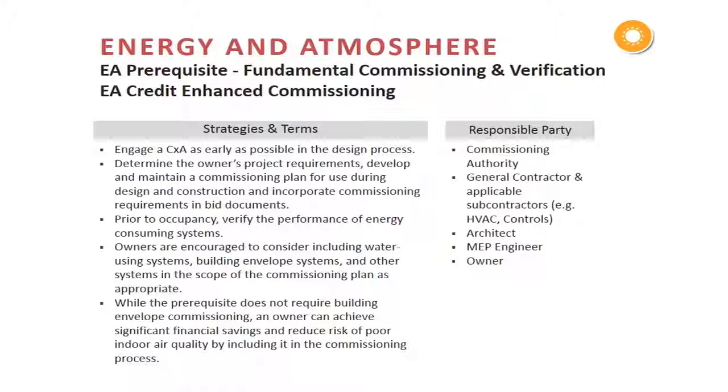Now, one other thing I'll mention here is that there's a huge variety, really, of these responsible parties. So the buck stops with the commissioning authority. They really are in charge of the entirety of the commissioning process. Not only that, their reporting duties are directly to the owner so that there's no potential for lost information as that information is disseminated from the commissioning authority. Now, additionally, the general contractor, hugely influential in this commissioning process. In many cases, they're actually doing the tests as the testing is observed by the commissioning authority. And then in addition, we have the design team and then ultimately the owner.